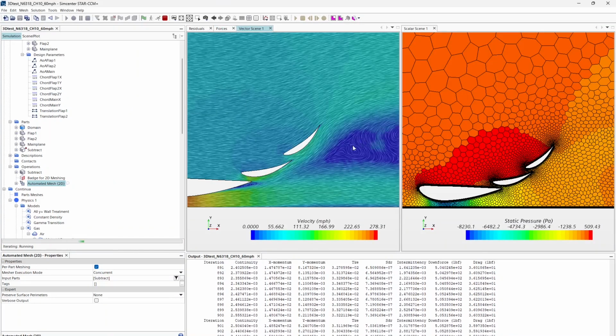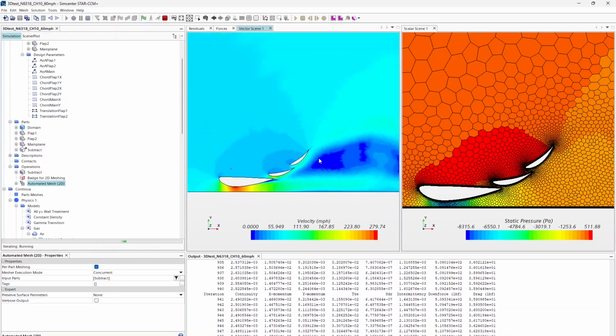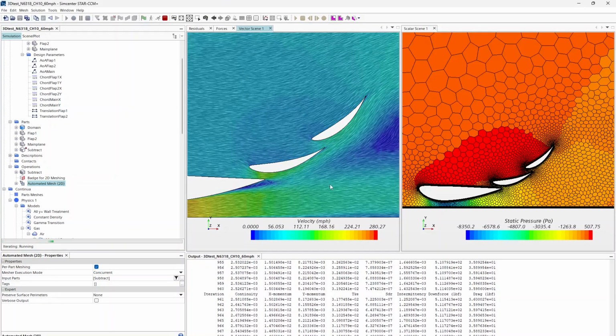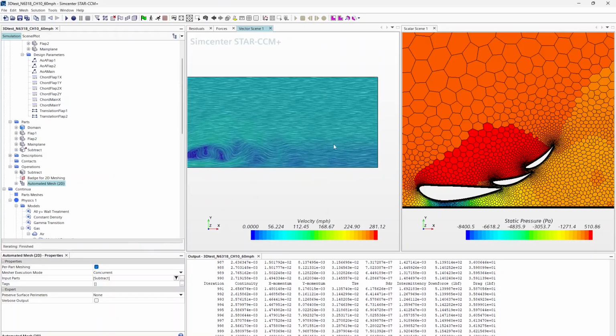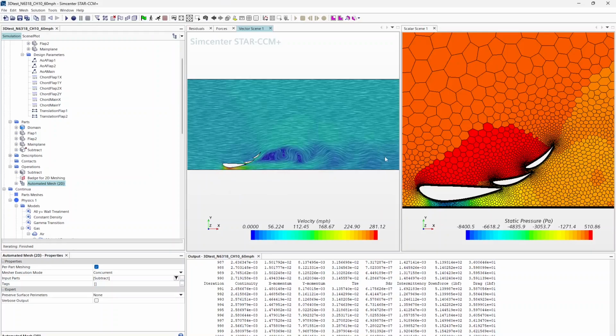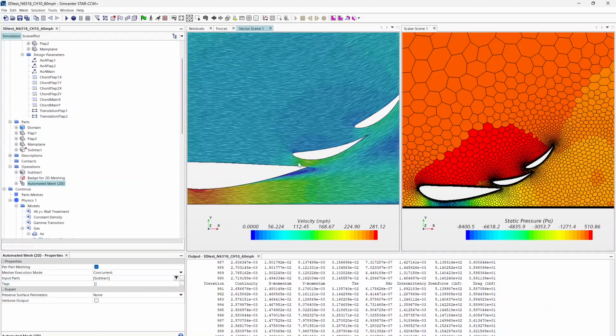But if your downforce goes down, that's a big red flag that maybe we need to reevaluate the changes that we made. And there still is some separation coming off of the trailing edge here now. It is much smaller, but much more turbulent, right? Because we used to have a big old wake behind it, and now I've got a much smaller wake. So my change of moving this down did help.